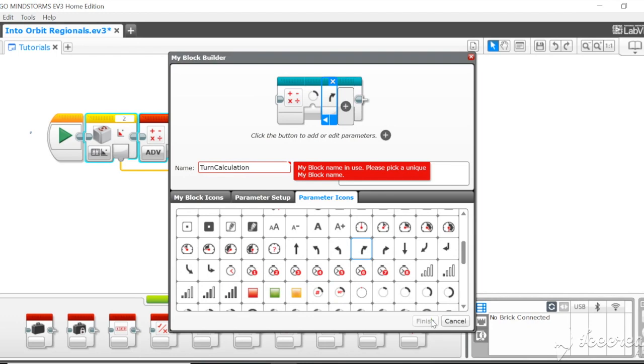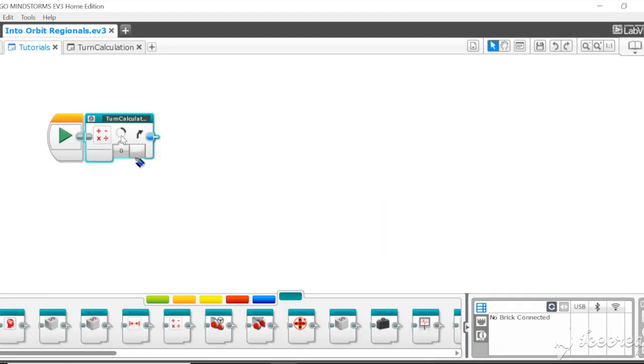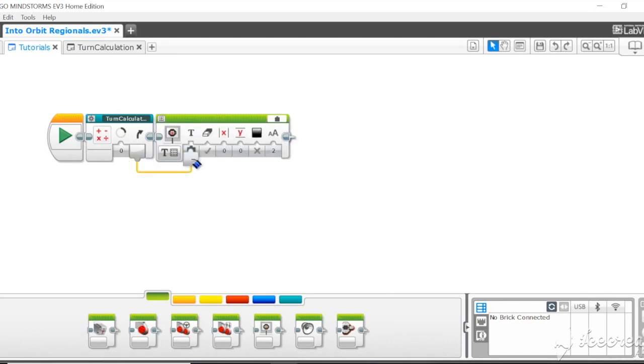and you hit finish. Okay, so now that you've got this screen, all that you have to do is take the wanted direction input and plug it into A, and then take the output from the maths block and plug it into the output section. The solution to the maths block will be here, and so we can use this anywhere. So, for example, we can put this into a display, and that will show us however far we are from 0. So if we're at negative 70, then the number we should be seeing is negative 70.